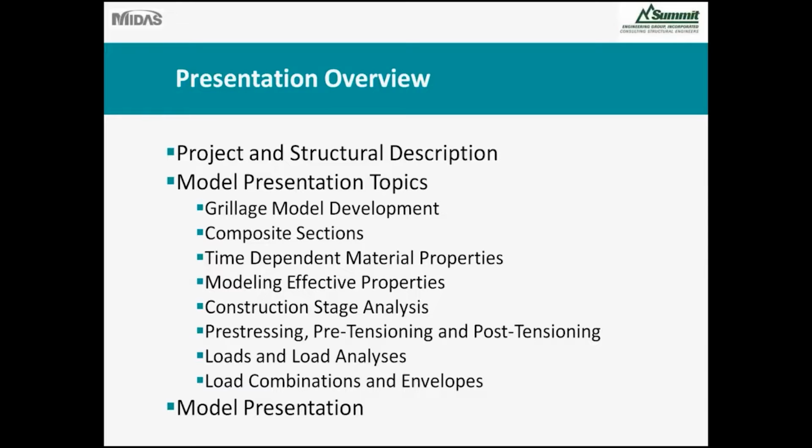So we'll be looking at a grillage model development with composite sections, time-dependent material properties, the effective properties, the construction stage analysis, including the boundary conditions, pre-stressing, both pre-tensioning and post-tensioning, the loads and load analyses, and then the combinations and envelopes.